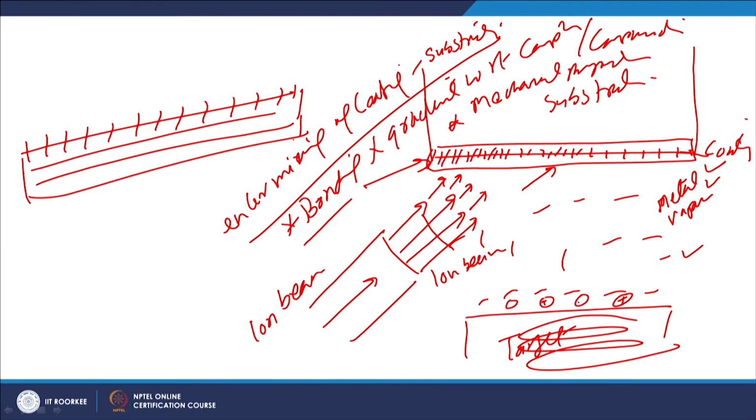Whether we are using vapor deposition, sputtering or ion plating, in all these cases, if the ion beam is applied onto the surface being modified, it will help enhance the performance and the properties of the surfaces in a much better way. This is achieved primarily due to the extremely good intermixing of the coating material with the substrate.